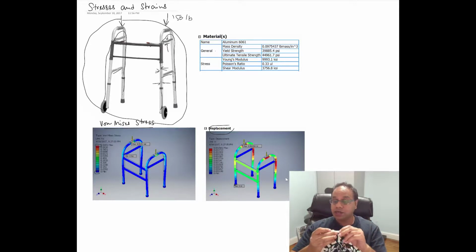Now if you take a ductile material, so imagine if this cylindrical piece over here was made of some grade of, let's say, aluminum alloy or steel alloy, and you applied this tensile loading, it would not be a flat cross section over here. It would be what we call a cup and cone kind of structure. So you will have a cone at one end, and you'll have a cup, and the two would fit. Okay, and that happens because when you apply the tensile loading on a ductile material, there is something called necking.